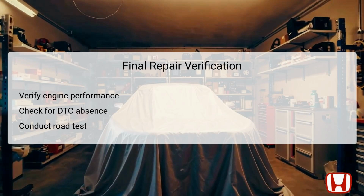After repairs have been made, a final verification step is necessary to ensure that the initial issues have been resolved. Mechanics should first verify engine performance to make sure that the vehicle operates smoothly without misfires or rough idles. Following this, they will check for the absence of relevant DTCs to confirm that none are present after the systems have been reset. A thorough road test is also prescribed, allowing mechanics to observe engine responsiveness under various conditions. This comprehensive check guarantees that the vehicle is back to optimal functioning and reassures the driver of its reliability.